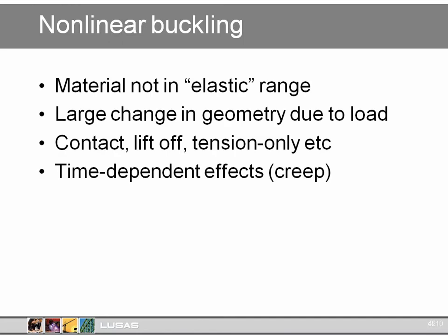A nonlinear analysis can take account of a whole range of things which are overlooked in a linear analysis of any kind, namely, when the material is not in the elastic range, a nonlinear analysis is required, when there are large deformations, when there is boundary nonlinearity, lift-off, contact, tension-only members, etc., when there is creep or some other time-dependent effects.